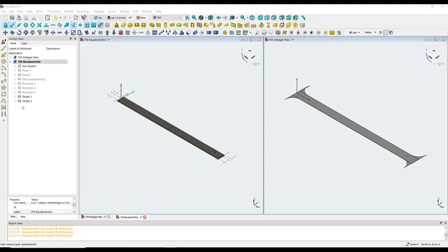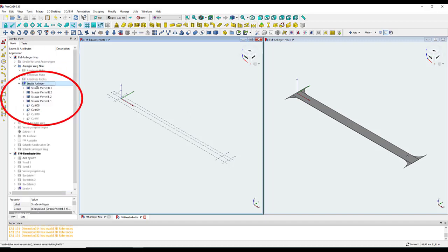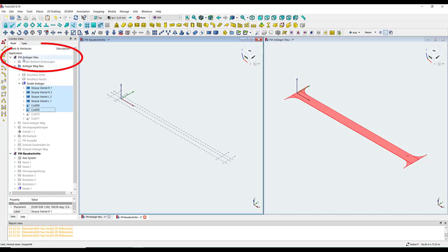I would like to build the last construction section with a linking. And then I switch to the Model New Building and look at the 6 objects that I want to transfer to the new construction section. And now pay attention to which is the active file. This is not the file in which the objects are located, but the file to which I want to link.